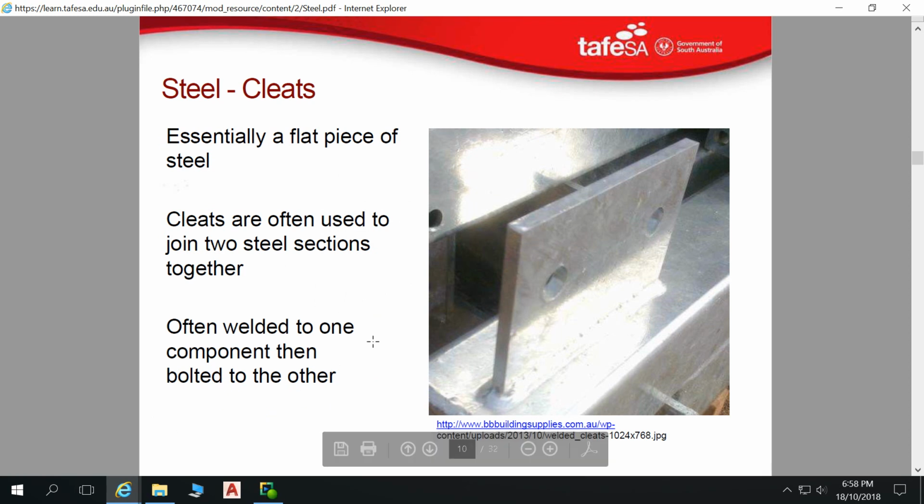So these steel members are typically joined together by cleats, which enables the manufacture of this to happen in a factory or in a steel workshop, and then it can be sent off to be hot dip galved. So that way we're not having to weld bits and pieces on site, because sometimes many of these components, if we were to join them all together in a factory, would be way too big to send for hot dip galvanizing, but then also too big to transport on a truck to get installed.